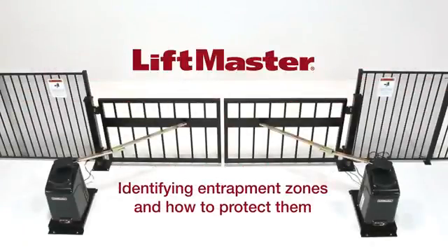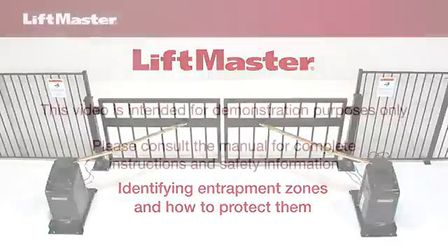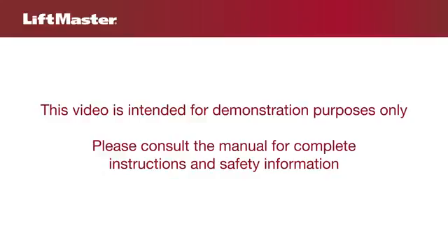This video shows how to identify entrapment zones. We'll also explain how to select entrapment protection devices for your installation so that you meet the requirements of UL 325. This video is intended for demonstration purposes only. Please consult the manual for complete instructions and safety information.